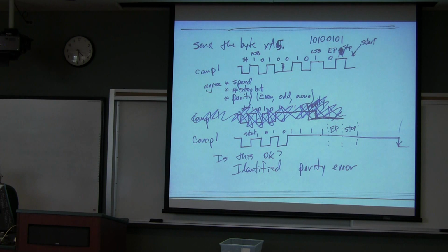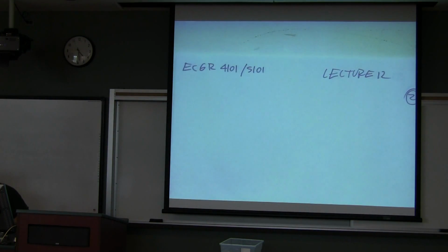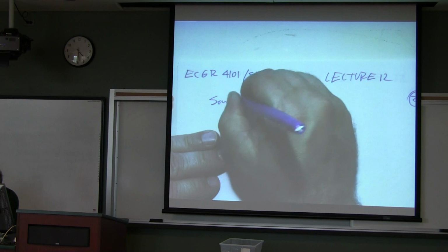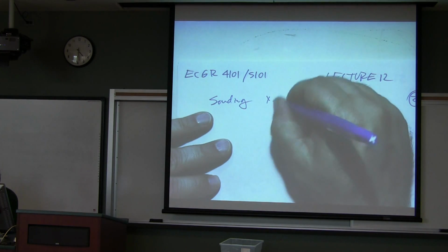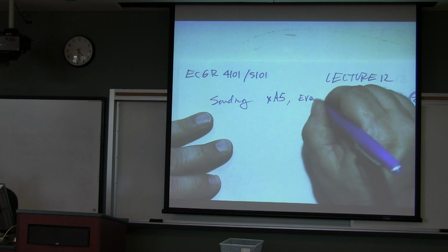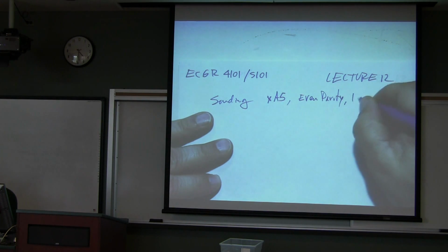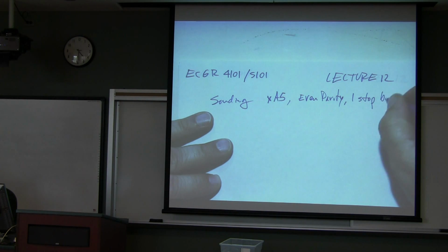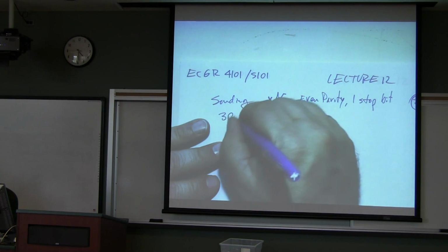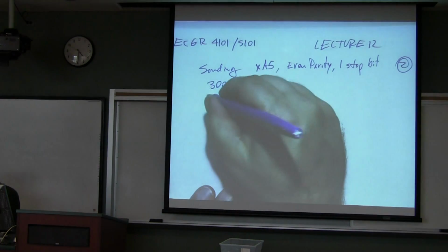By the way, how long does communications take? Let's look at an example. Let's say, again, we are sending the hex value A5, even parity, 1 stop bit. We're sending at 300 bits per second. How long does this actually take?